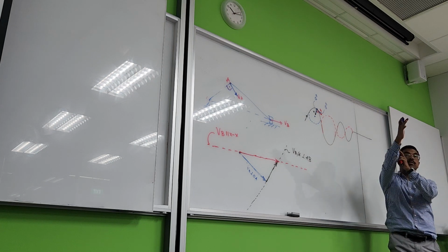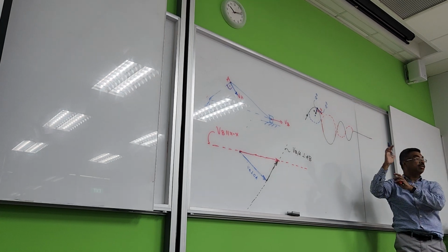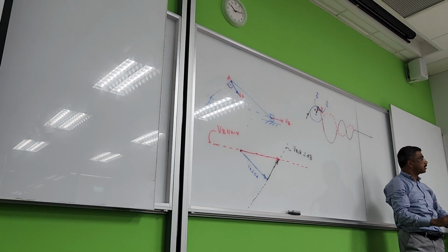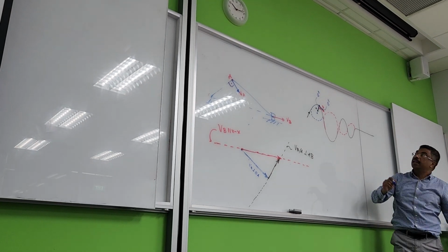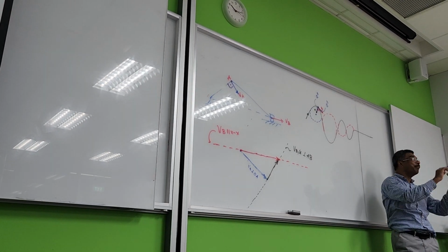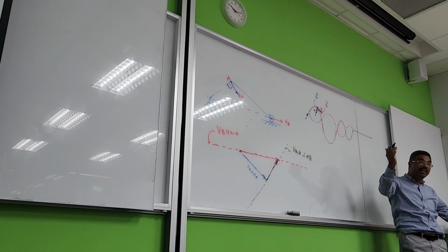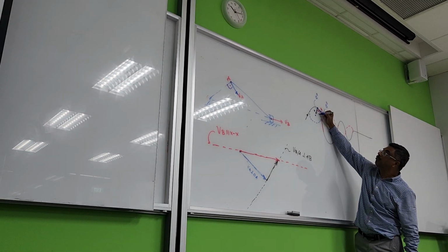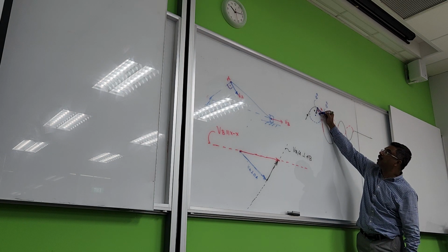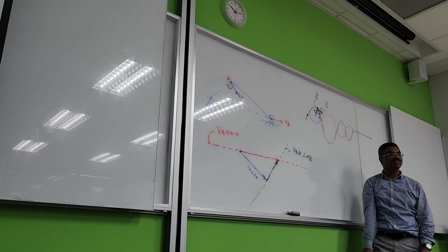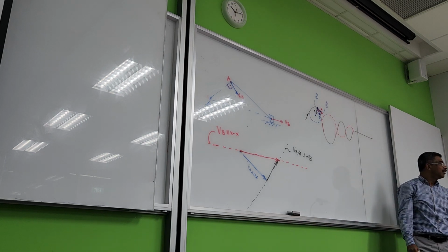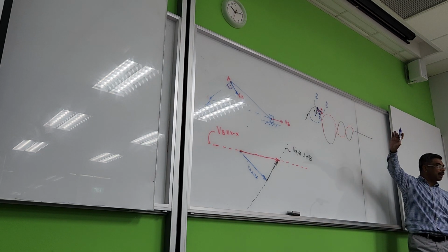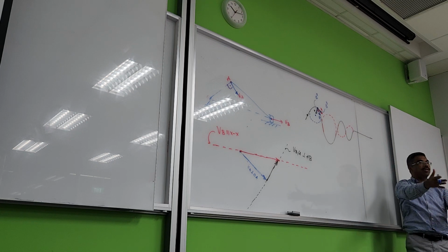In the tangential direction, the t direction, will be our tangential component of the acceleration. Clear to everyone? And now, if both of them have some value, they can be equal, they can be different, doesn't matter. You can combine them in a parallelogram, and then the absolute acceleration will be this one, A. Because for two vectors, you make a parallelogram, you draw a diagonal, and the diagonal is your absolute vector.